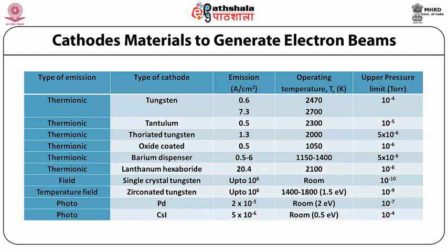Field emission cathodes are generally best but most expensive. Here the emission occurs in lobes because of crystal phases present at the surface, and here the emission can be unstable. Various types of cathode materials used in E-beam lithography are tabulated below.